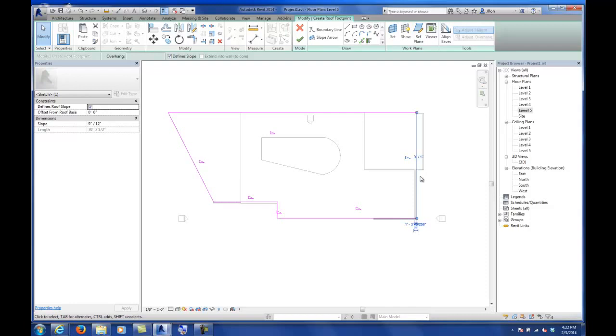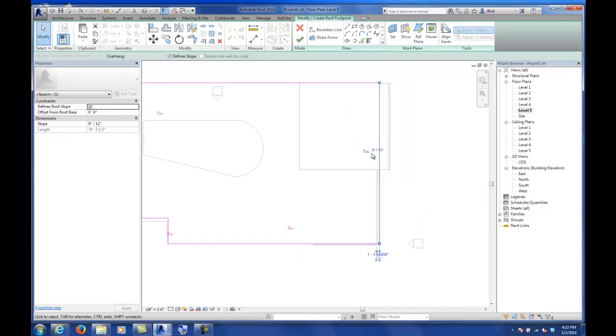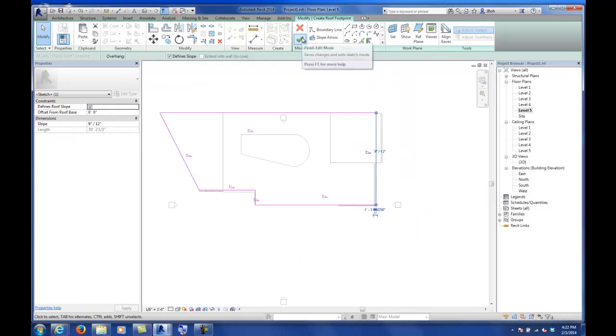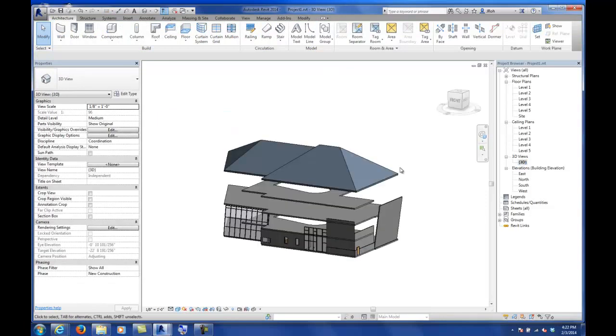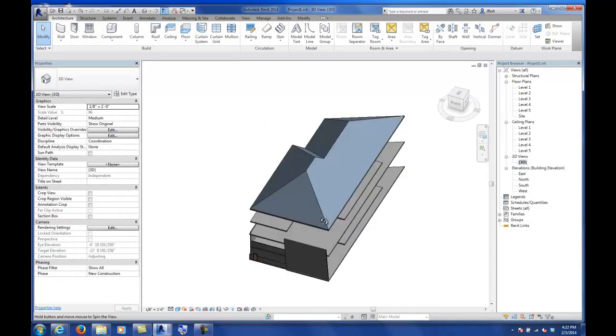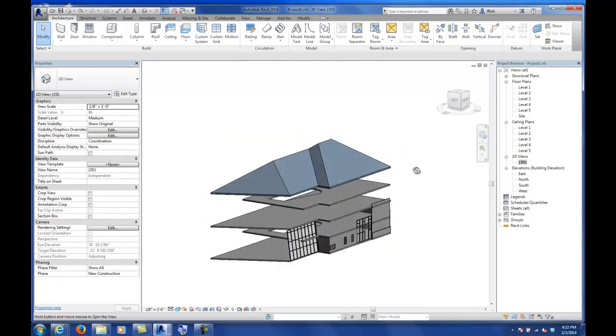And now, because of the hinge symbol, it's going to hinge up, and it's going to keep going until it meets the rest of the roof assembly all the way around to whatever your setting is. So by default, it's something like 9/12 pitch, so that's fine. Let's just go ahead and hit the checkbox, cancel out of that, and then it's made your roof assembly, and just put that together real quick.